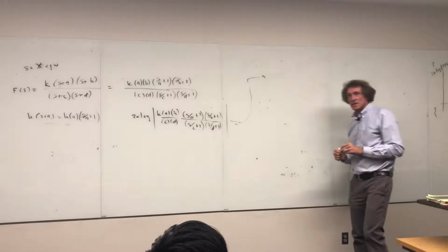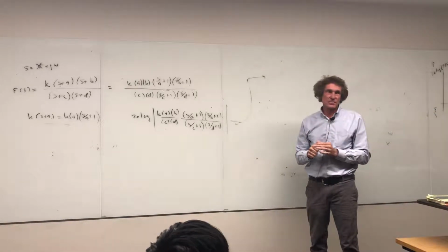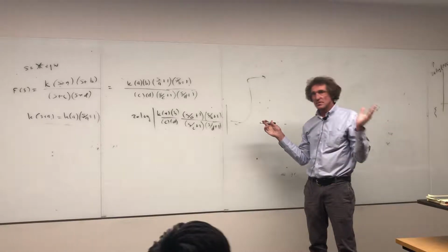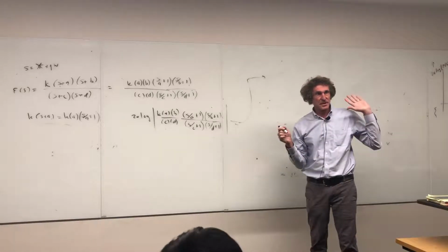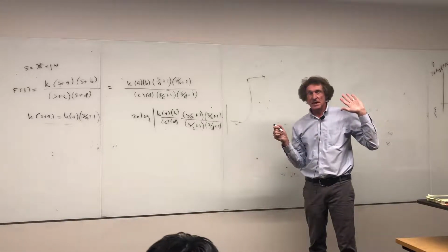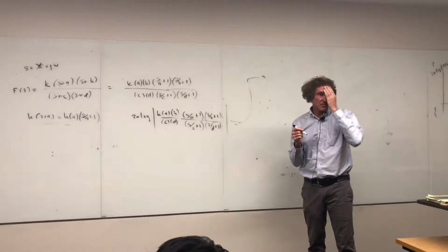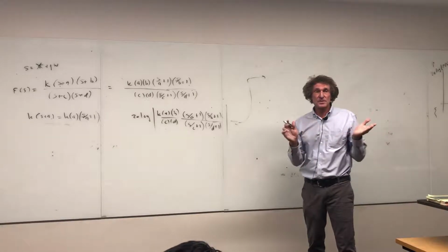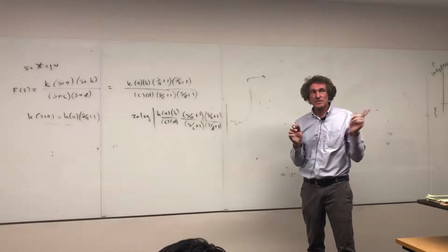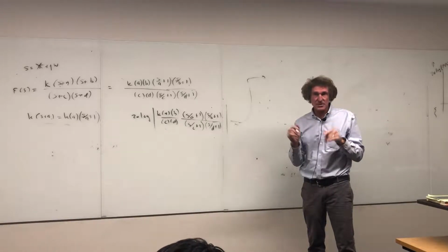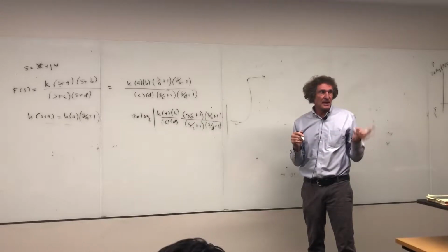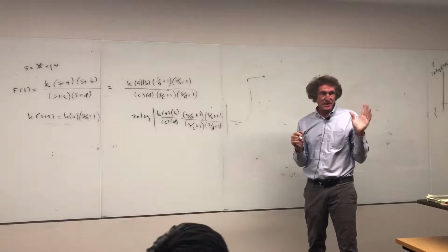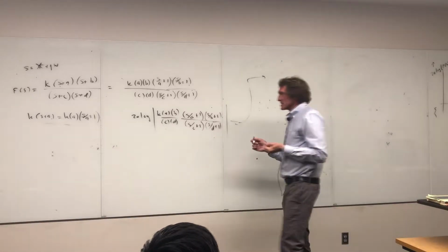Something else I'll tell you. In engineering, you use Bode plots for everything. Controls, electromagnetics, any kind of circuit design that involves frequency response, you're going to use Bode all the time. One key thing, remember: if it's power, it's 10 times the log of the function. If it's voltage or current related, it's 20 times the log. That's the one thing you keep your head on straight about, or else you will mess things up.